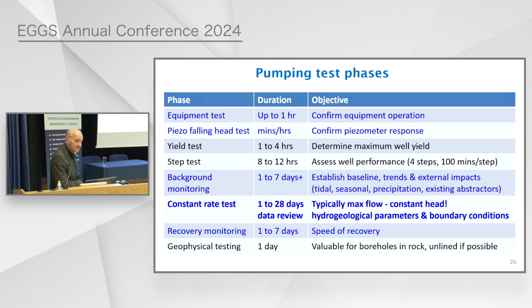Yield tests are just really short-term tests. See how much we can get out of the well. Sometimes worth doing. Step tests, I mean, they're really designed to tell us about the efficiency of the well. I'm confident that I've installed the most efficient well. I don't need to know what the efficiency is.